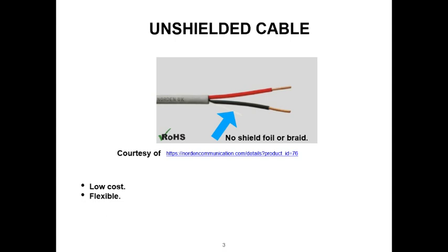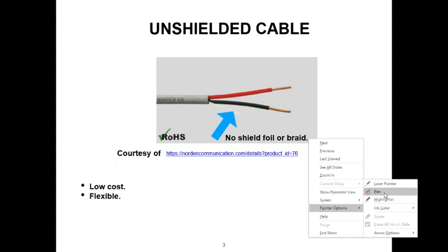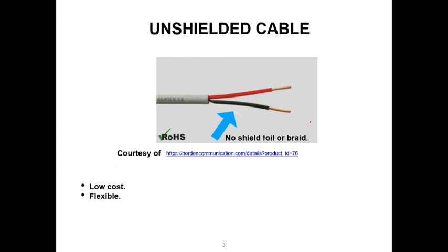So in this image, you see we have two wires, and inside the wire they're going to be twisted or wrapped around one another, and that's to minimize crosstalk and external electrical interference. But there is no braided shield. Let's pull up my pointer here. So here we have just the two conductors. This is obviously the PVC or whatever it is, the jacket. Okay, there's no braided shield.